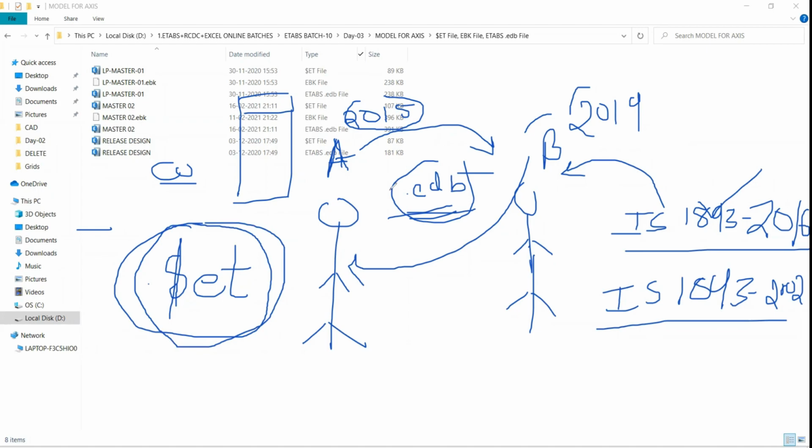So when you open your file from lower to higher or higher to lower, taking the $ET file, suppose I am going to open a 19 version file in 15. The 2016 earthquake loading is there in the 19 version file, and I am trying to open it in 2015. The software gives you a pop-up about all the advanced loading and all the 19 version advancements that are not present in 2015. If you are willing to open in 2015, all the advanced options will be discarded in the opened file. So that is the difference when the version changes.